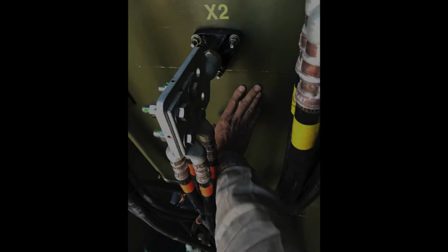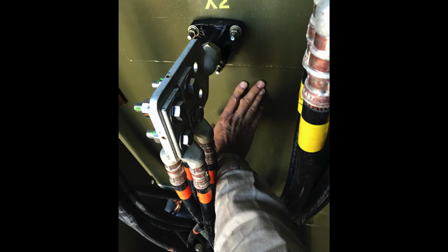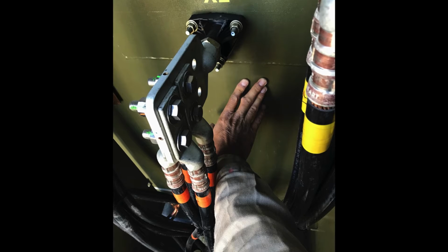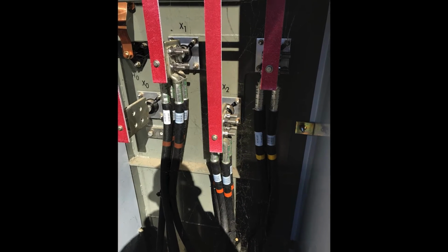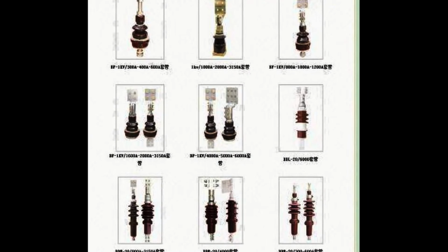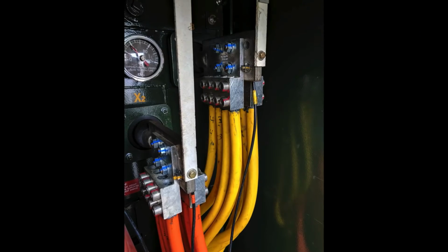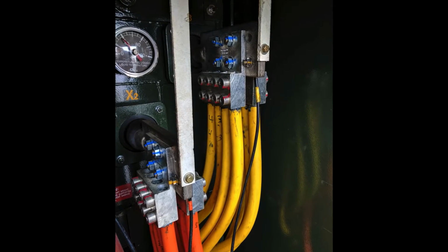The low voltage or secondary bushings provide the necessary insulation between the windings' electrical connection and the main tank, which is at earth potential. They seal in the oil and provide an external cable termination to the secondary windings. The insulation is usually porcelain or epoxy resin. Low voltage bushings are typically just bolted lug connections.